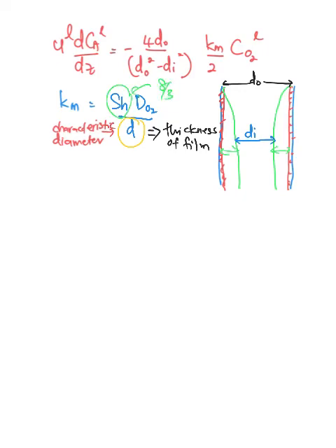The characteristic diameter is equal to the thickness of the film, 0.1 centimeter. So a liquid phase reaction on the surface of catalyst is quite complicated compared to the other three cases we learned in the previous falling film example.